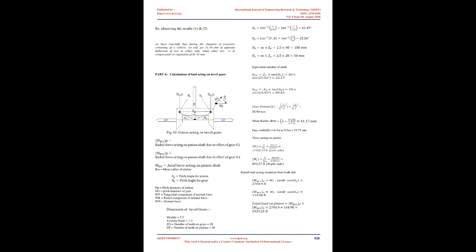So in the present invention we have configured a mechanism consisting of 3 mitre-type bevel gears which can be engaged and disengaged. In the engaged position of the gears, the anti-roll bar will provide continuous traction while cornering. In the disengaged position of the gears, it will improve riding comfort during uneven road conditions. The name of the system itself implies that it can deliver some excess amount of roll stiffness to the vehicle. The arrangement of components and working efficiency of the gear mechanism is maintained in a way that stiffness can be varied according to various road conditions.